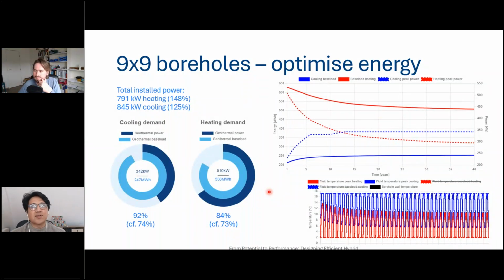Okay, so that's interesting, because the assumption here is that the ground has homogeneous characteristics. Yeah, that's a basic assumption behind all the models related to ground source heat pumps. The only way to get around it is by actually doing numerical simulations. That's just the way these things are modeled using g-functions.